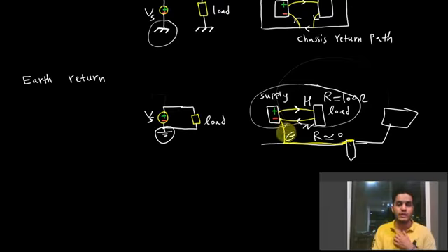That's all that's going to do. There's no current actually flowing here unless there is a short or a hot wire coming loose inside the device, in which case, instead of flowing through you, who have higher resistance than the earth, the current is going to flow instead to the least resistance, which is the earth, and in that fashion it's going to protect you.